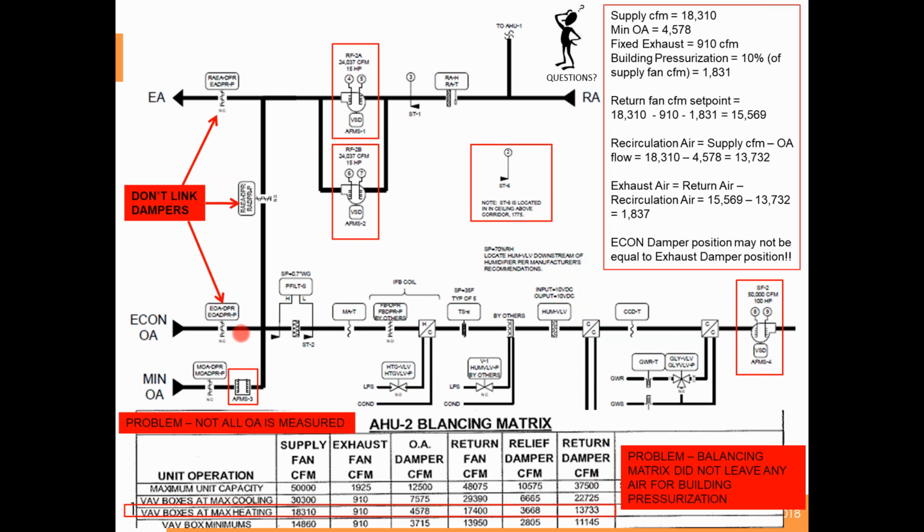And just a word of caution, this is kind of a side tip, that when you do this, as soon as the economizer opens, which is a much larger damper section, you will read below your minimum outside air. It doesn't matter that this damper is 100% open. It has a greater pressure drop than the economizer. So this is one of those where your trending data is going to get a little skewed and look a little weird. And again, if you're actually trying to measure things and use the measurement of outside air, this would not work at all.